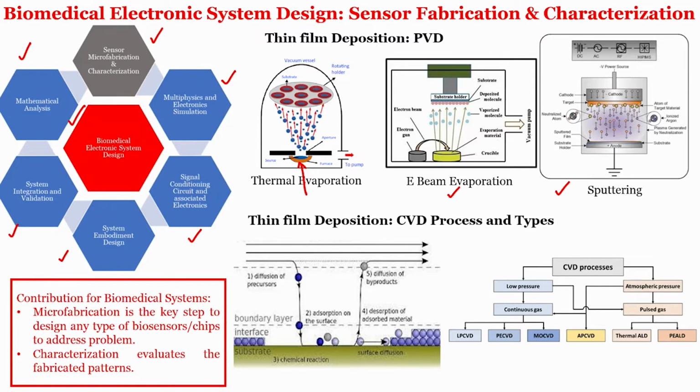The advantage that we have seen in CVD compared to PVD was that it will cover the surface or it will cover the step better than the PVD technique. So, step coverage is better because here the chemicals are reacting at every step. For example, if this is the step, let me just draw it here.